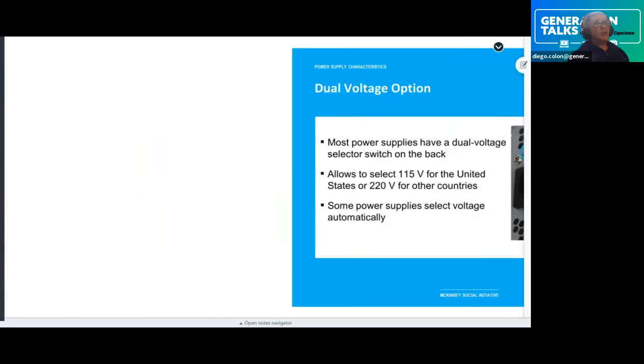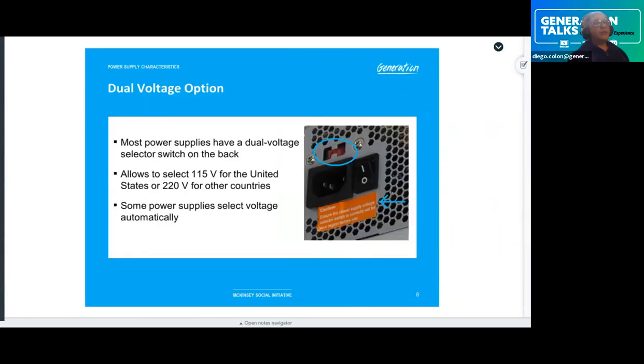Okay, when you were talking about a laptop, or are we speaking about, for example, a simple little adapter that you plug in to charge a phone or anything like that? It has to be rated for the actual voltage that you're plugging in, and that adapter will then convert it to the DC that it's required. But the equipment or the adapter must be able to handle the actual voltage that's coming in.